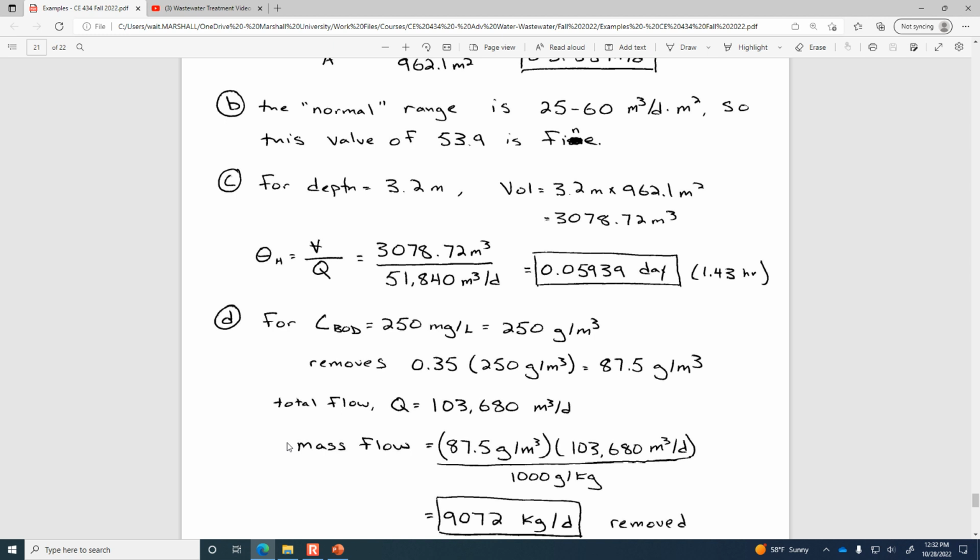So if we had dumped this wastewater directly into a stream, it would need 9,000 kilograms of oxygen per day to break down the waste. So what we're going to do instead is break down that sludge. The stuff on the bottom that we're sucking out, that's going to be broken down. It could happen either anaerobically in some sort of a sludge digester, or the sludge can be thickened and dewatered and then applied over the land, and the BOD could be broken down that way.